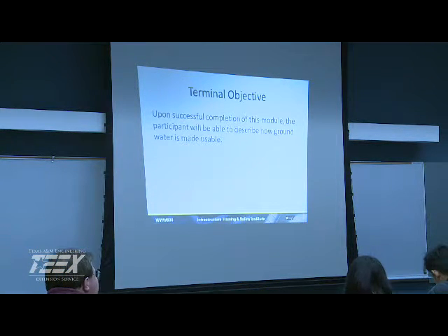Because we can go in there and figure out our water level, the diameter of our pipe, and the depth of our well casing. We can figure out how much we need if we have to disinfect it to a certain level, 50 milligrams per liter, something like that. We need to know how to do those calculations. They're very beneficial.